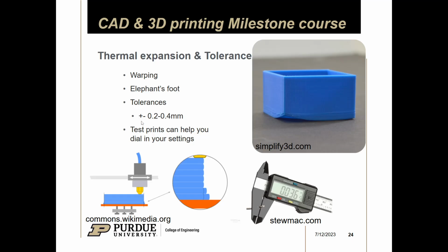So typically your prints will be slightly oversized. So you might want to compensate for that in your design, right? One of the things I do very often, I love M3 screws. So obviously M3 is 3 millimeters in diameter, but if I want to put this through a hole, you need to add some clearance, right? So I maybe make the hole 3.2 millimeters wide. So when I put the bolt in, it'll just slide through without any issue. If I made it just 3, then it'll interfere and I'll have to screw through the plastic or the filament, whatever material I made it out of.